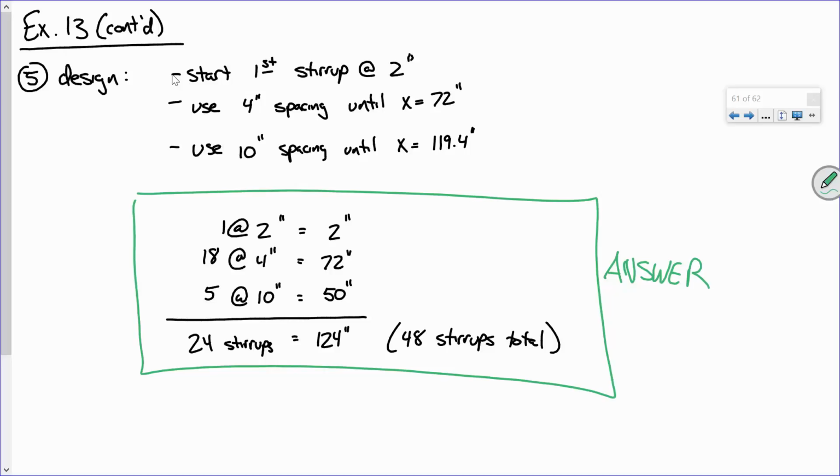It'll say that in the problem. Begin your first stirrup at 2 inches, regardless of what you do. And I want you to use at most 2 increments of spacing: the stirrup spacing at x equals d, or Vu star, and the maximum allowable. So don't do any stirrup increments in between. You do that, we should all arrive at the same answer. So that's to QA/QC the homework.